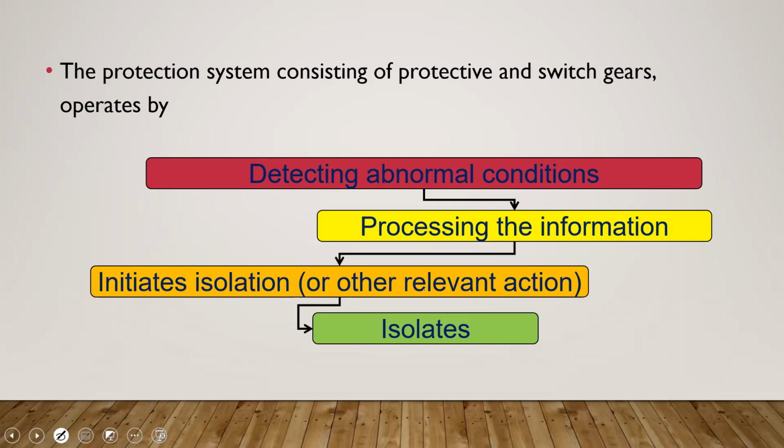The per unit current that you would have calculated was 8 or 10 times your load current. The per unit current was 10 point something, all right? So I want you to think about that multiplier in terms of what the regular house breaker would be seeing.